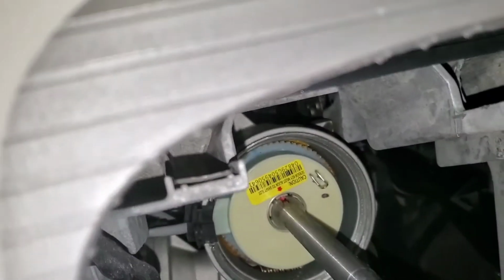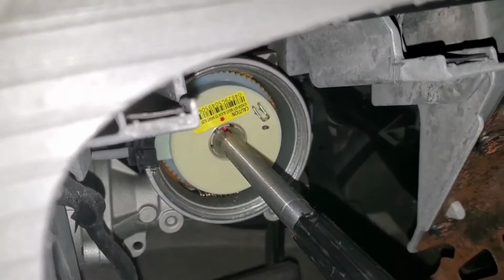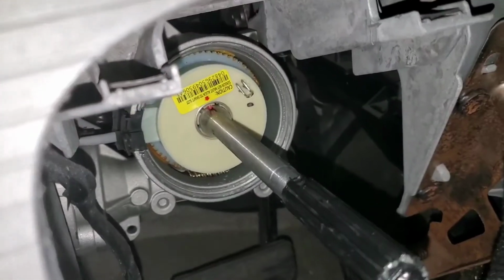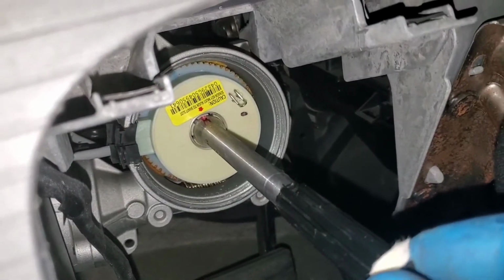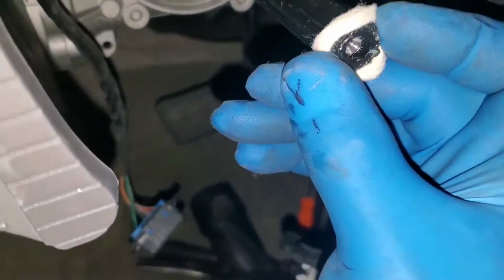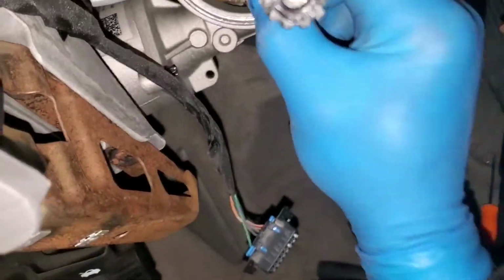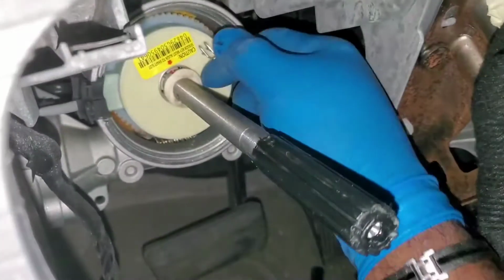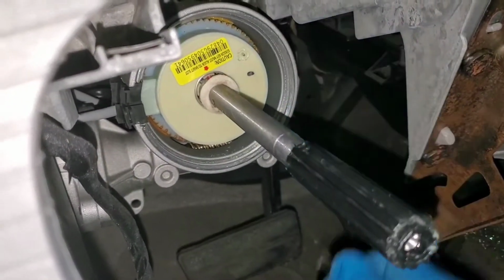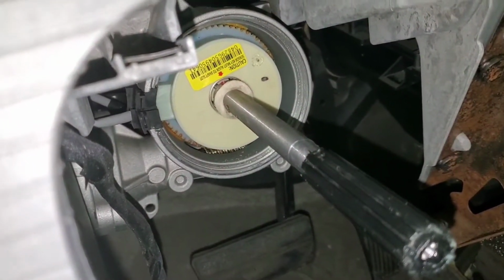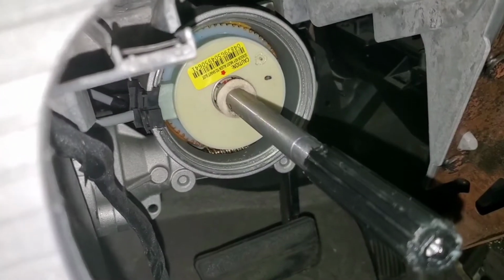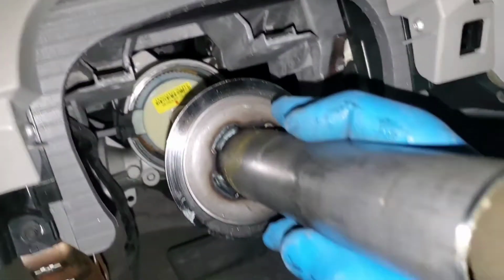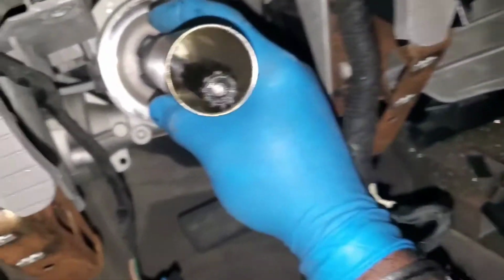So what I'm going to do is pull this pin with my little absorbent ring. Slide the new absorber ring all the way down there. I'll pull the pin, put our torque tube on. All right, pin's pulled. Where's my torque tube? All right, slide that all the way on.